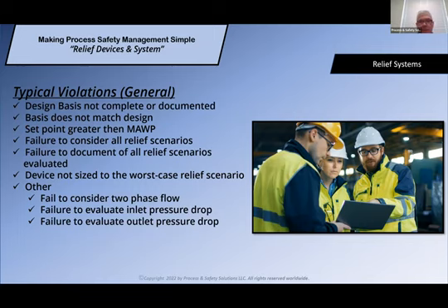Set pressures can be different. Also, back pressures can be different. For example, you actually did the calculation for back pressure and you had a superimposed back pressure of 10, but the relief valve was not sized for it, and set pressure was not adjusted to match that back pressure. Also, set point was greater than the MAWP. Remember, we said if you have a single relief valve, that must be set at no higher than the MAWP of the vessel.